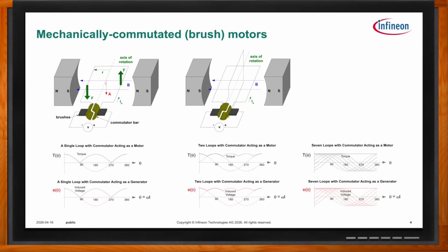I'm sure you've all seen something like the graphic on the upper part of the screen here that shows two permanent magnets on the left and right of a coil. It's a single wire coil representation here. So this is the classic simple motor. We call it a DC motor because you can apply a DC voltage to it, and that mechanical cylindrical commutator takes care of switching the polarity at the right time.